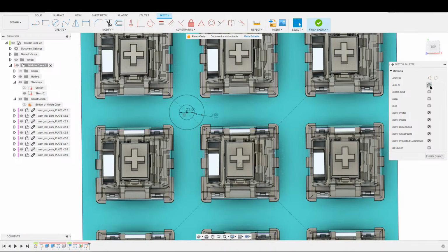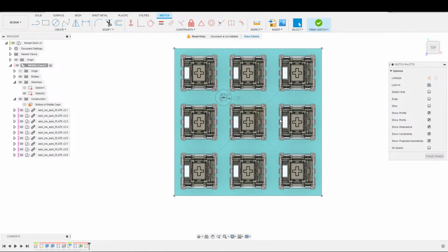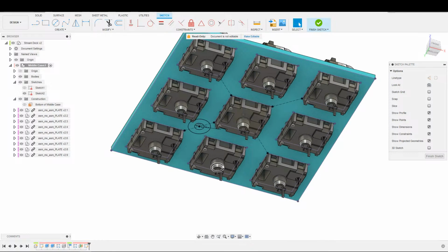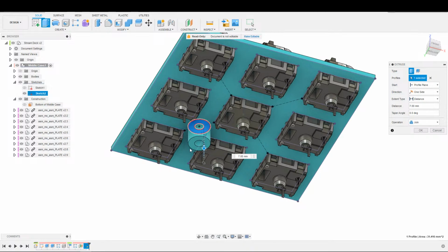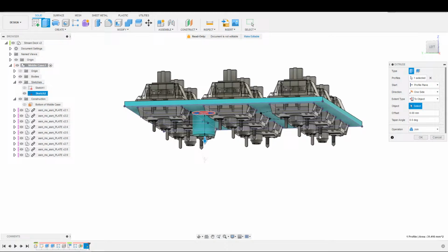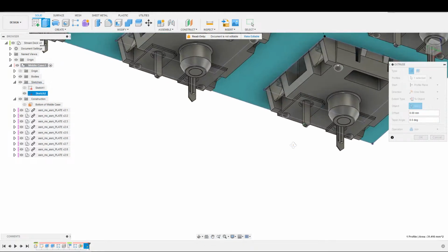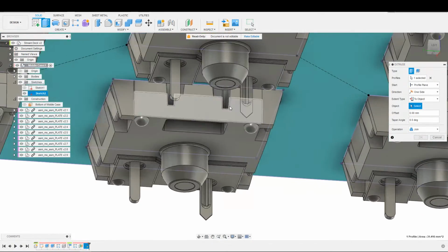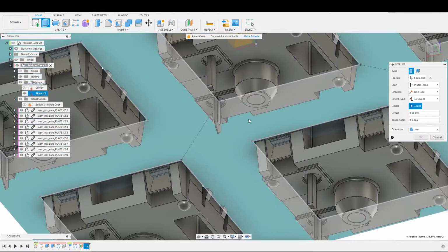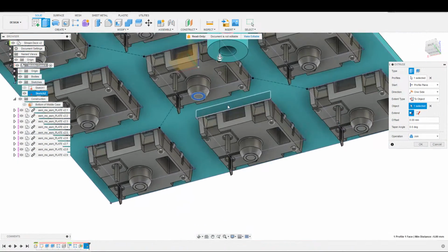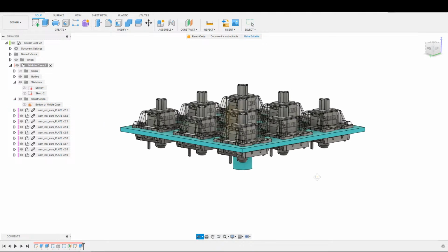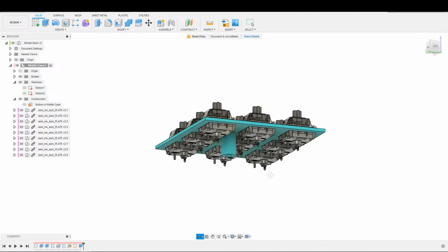So at this point, we can bolt this plate down. The other option I was going to say is on the bottom case, we could just have a press fit on these. Let me actually bring this down just so that you can see what it's going to look like. Distance to object. It's hard for me to tell what is the furthest down object on this model. I think I'm going to go to this face, and then I'm just going to give ourselves another, let's say 5mm,